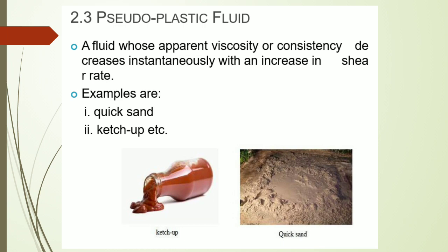It will try to increase its shear, means it will try to change its shape here. Same thing if you take ketchup. If I pour the ketchup, what happens? It will try to change its shape or increase its shear rate here. So that is what the pseudo-plastic fluid says here, whose viscosity or consistency decreases with an increase in shear rate here.